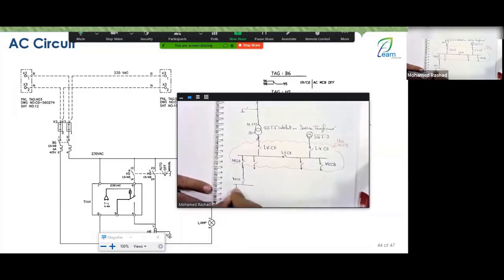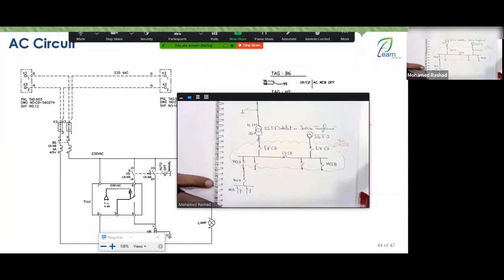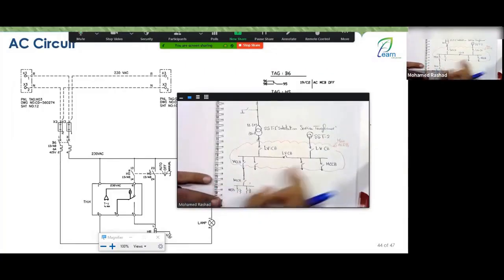And it exits from here with a set of MCBs, which are drawn like this and like this, a set of MCBs, which are miniature circuit breakers. It exits like this, in this manner. Of course, this is drawn like this and drawn like this, which is the symbol of the miniature circuit breaker. Okay, nice. But is it just one incomer? No, there could be an incomer and another incomer coming from the other section here.